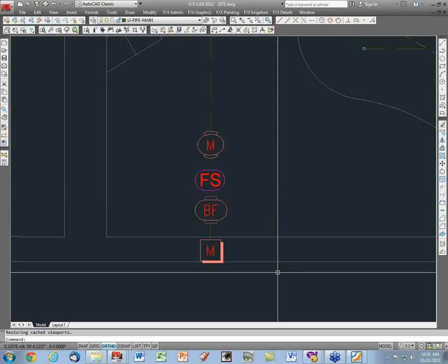You're going to stop the flow with the master valve no matter whether it's before the sensor or beyond it. It may be the condition of the job where you want to keep the pipe full of water as it goes through the flow sensor. It will give you better totalizing and things like that, but it can go either way.